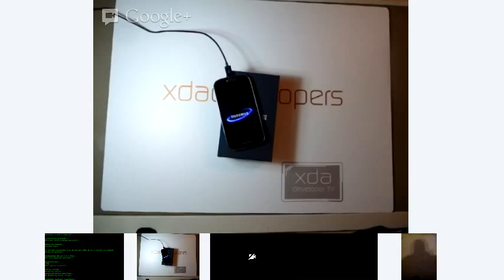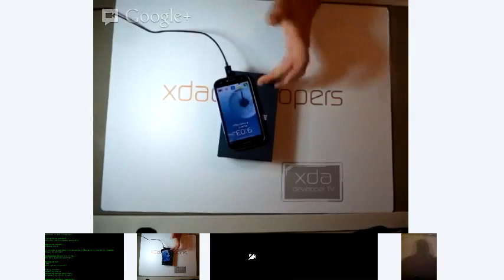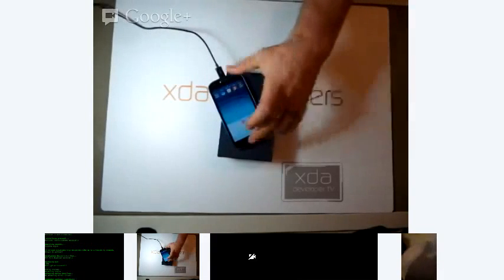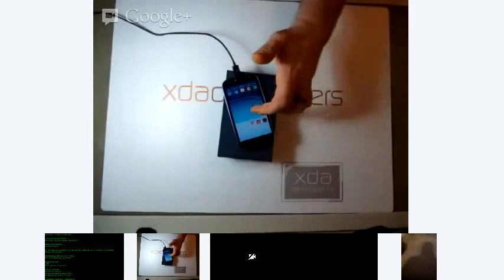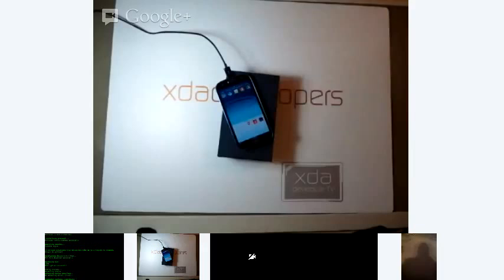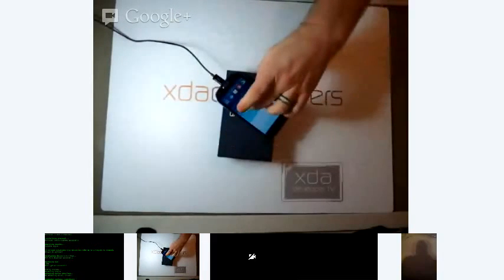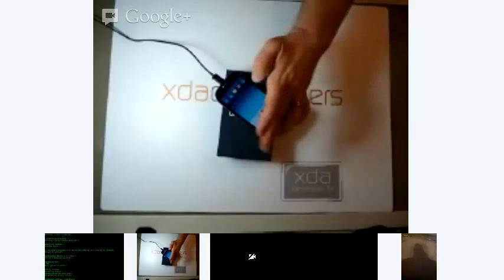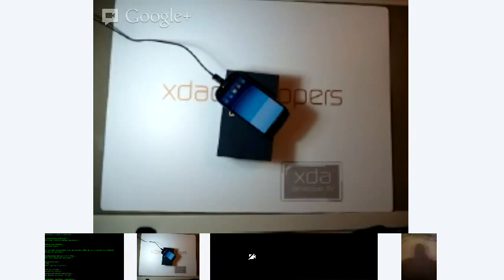All right, there you go. Now you notice that it's kind of jerky now. It's actually sending all of the UART output, and there's a ton during the boot sequence. Because it's sending so much output, it's actually locking up the processor a bit, trying to get all that output out of the buffer. So it's a little bit jerky on the startup, but other than that, there should be no real difference because it's basically just sending the dmesg output to the UART port.